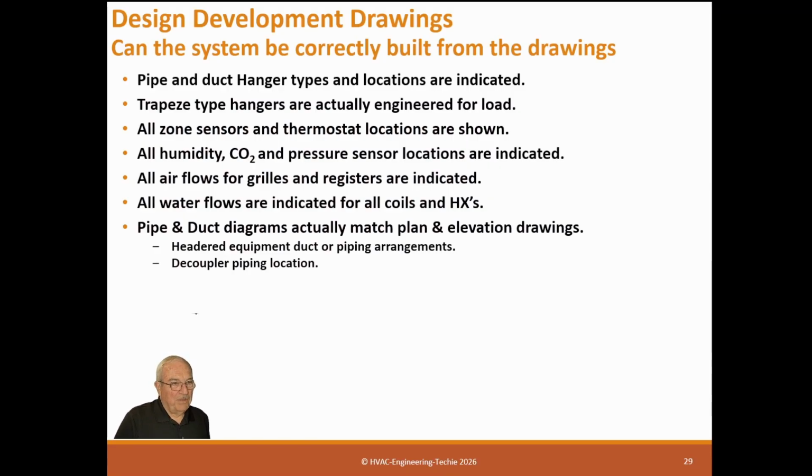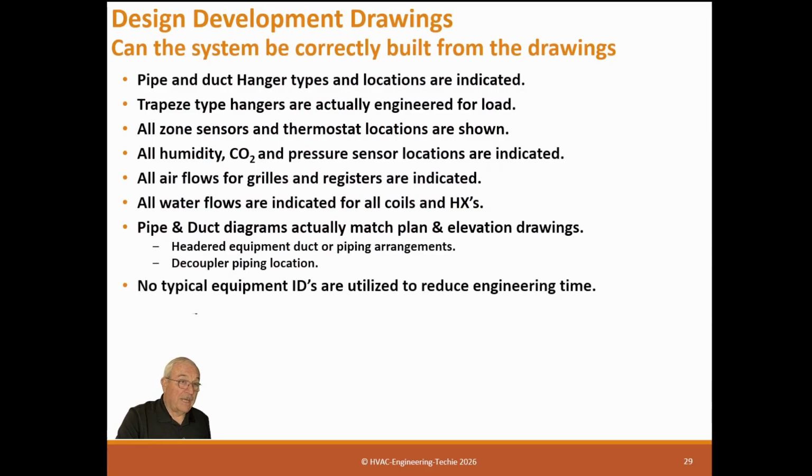But when you go to the plan, the way it's installed and the location and the conflicts it has to go through, they end up putting the decoupler in backwards or on the other side of the return pumps. So basically, all the water goes to the decoupler, whether it's going to the chillers or to the field. This means you can't run them above 65% capacity of the plant. So it's really important, but it happens a lot.